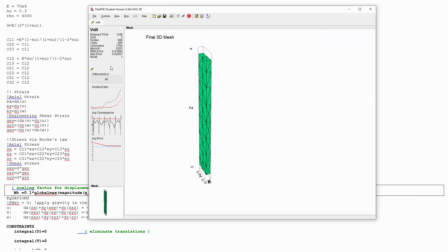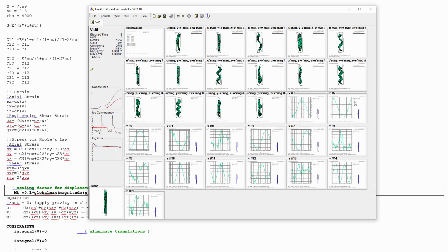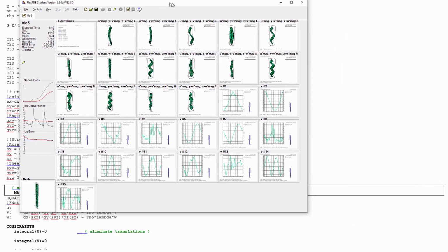Notice that Flex is arguably finding higher modes here. So part of what it's doing is varying around energies and values of lambda to see what works, zoom in on things and see if it can locate any modes in between and find what really should be the first 15 modes. Okay, so even with error limit set to 0.01 rather than the default much smaller error limit, this simulation for 15 modes takes about 80 seconds, so it's quite a long time.